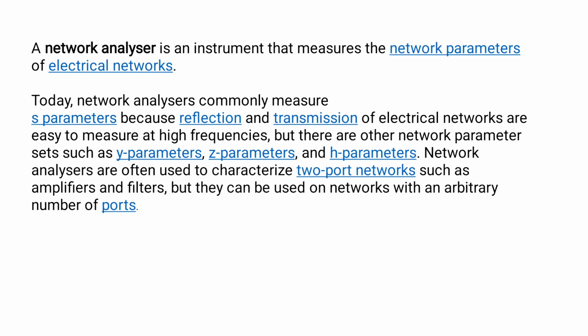Actually, a network analyzer is an instrument that measures the network parameters of electrical networks. The network parameters are S11, S21, S12 and S22, which are measured by using the network analyzer. Today network analyzers commonly measure S parameters because reflection and transmission of electrical networks are easy to measure at high frequencies. But there are other network parameters such as Y parameters, Z parameters and H parameters.